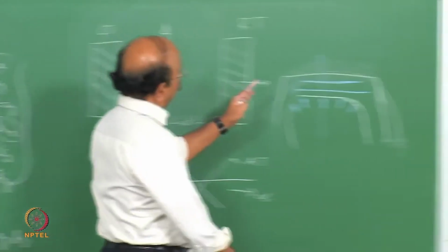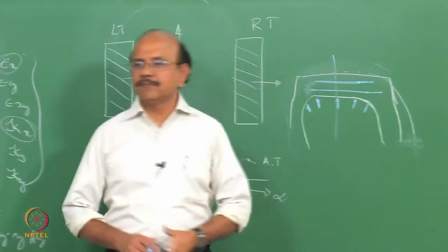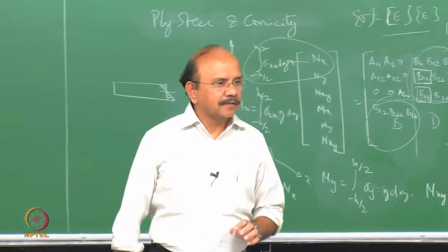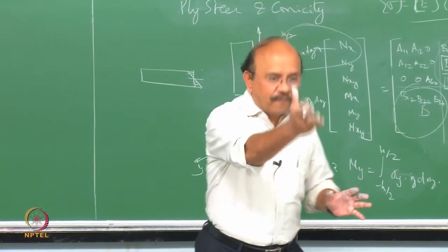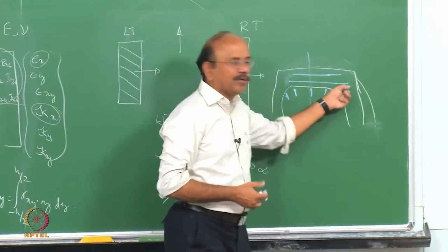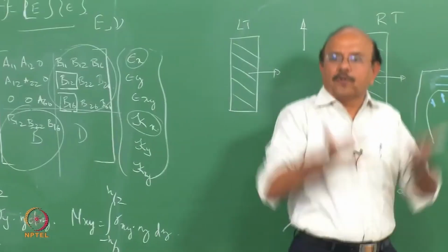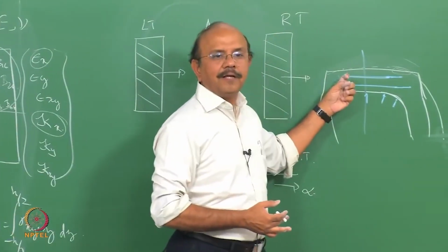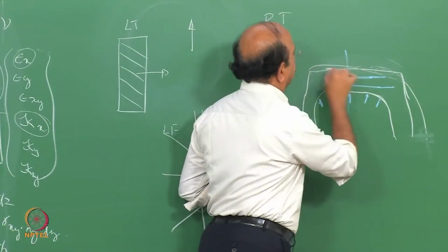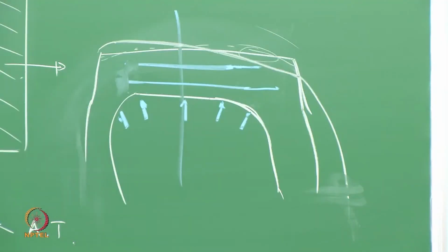So what do you conclude looking at the left hand side and the right hand side? Radius in the left will be higher. Fantastic. So radius in the left, when I inflate it, will be higher because this is going to be stiffer. So these material elements sitting here are not going to move to the same extent as to the left, and hence my tire is going to become something like that. In other words, my tire is going to look like a truncated cone.